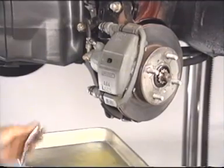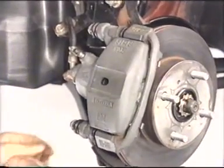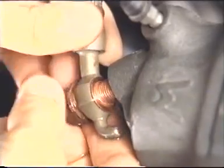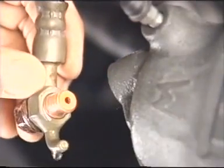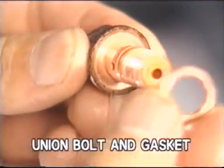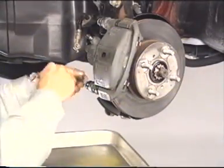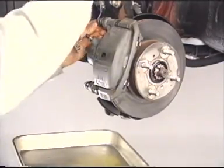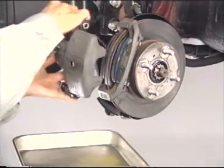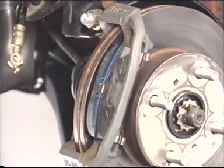Now, let's go on to the front disc brake wheel cylinder assembling procedures. Remove the union bolt and the 2 gaskets from the brake cylinder. Prepare a container to collect brake fluid and remove the flexible hose. Grasp the sliding pin and remove the fixing bolt and cylinder from the torque plate. Remove the 2 brake pads.